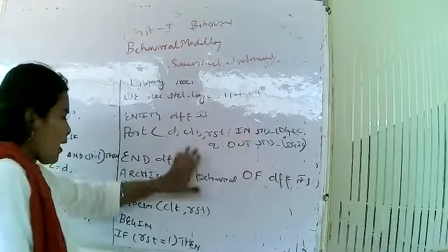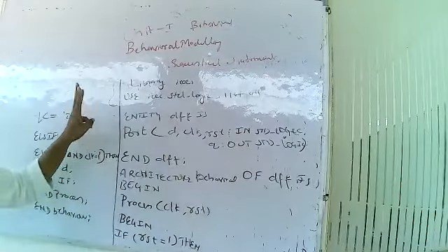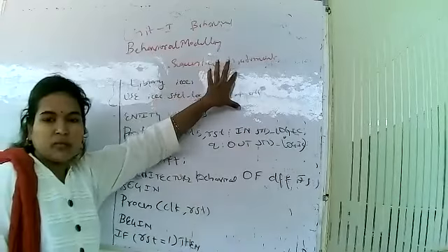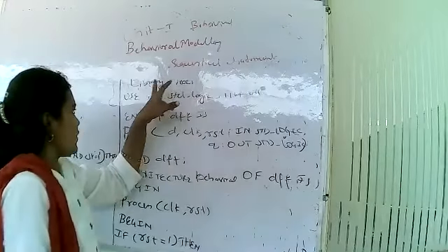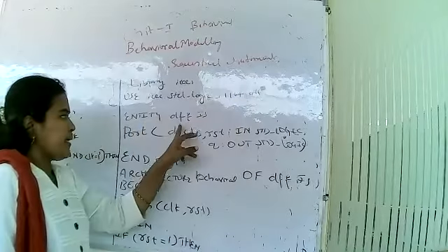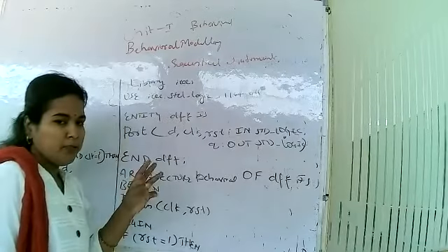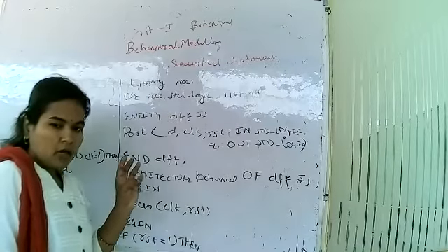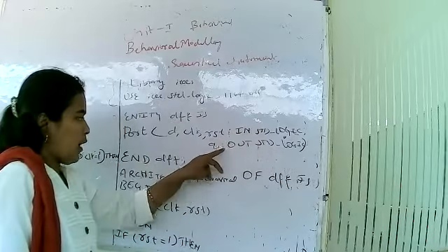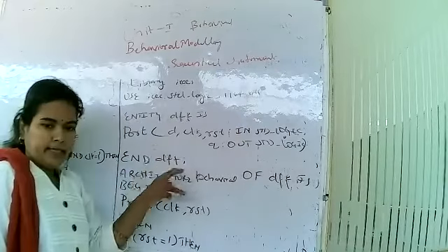So this is an example of a process in behavioral modeling, where we use sequential statements, taking the D flip-flop. I have written the program, so now I will explain it. It contains three sections: library, entity and architecture. The library shows which functions and procedures you are taking, here IEEE std_logic_1164.all. Inside the entity of the flip-flop, the inputs are D, clock and reset, RST is the input and Q is the output. Now it's the end of the entity.